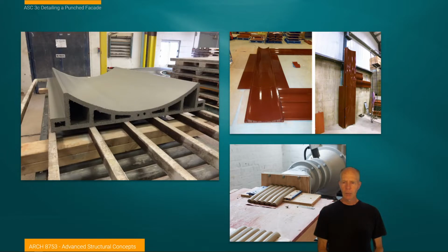I don't think I've gone into any depth with that, but here we have one of the panels that would be on that building. We're looking on the left side at what would be green terracotta, freshly out of the extrusion die. Most of the time it has this grayish color. It doesn't get typically that brick-like terracotta color until it's fired. Firing is just the baking at very high temperatures of this material to actually transition it from being a clay to being more like a ceramic product. So there's a real sophisticated, or really interesting, change in the chemistry of the material as it is fired.